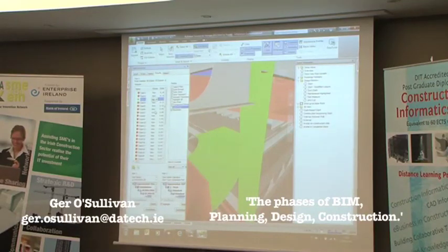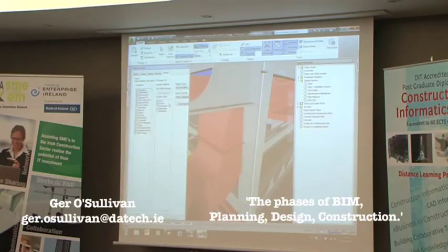Then when we bring in the updated model next week, all the new clashes become old clashes, and if there are any fixed, they will be removed from the actual report. So again, it's just a different way of working. It's being able to pick up intelligent information and then present it in a format that is very visual. You can export that report out to HTML, or any format like that, where you can then place that into a report that you would be using in a design team meeting.